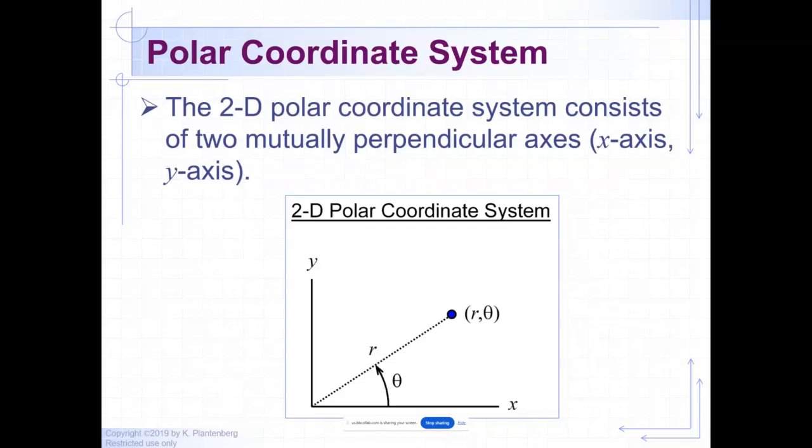All right, so polar. Relative commands or relative coordinates should start with an @ symbol. Funny thing is there's a setting called dynamic. When it's on, all your stuff is input as relative. But I always try to use the @ symbol just so that I get in the habit of knowing that I'm doing relative.